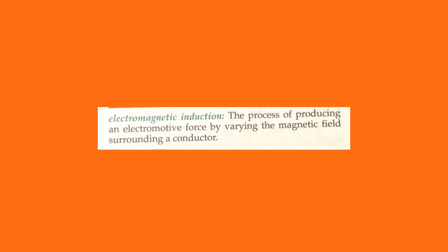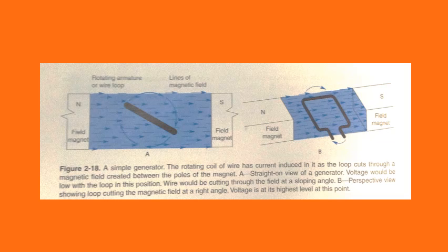The strength of the electron flow in a generator is increased by 4 factors: a greater number of turns or loops of wire in the coil, a faster speed of the conducting loop rotation, an increased strength of the magnets, and positioning the moving coil at right angles to the magnetic field lines of force. See figure 2-19.